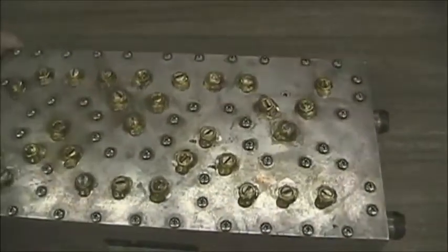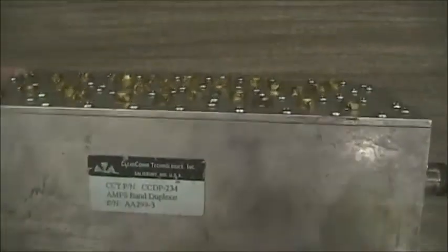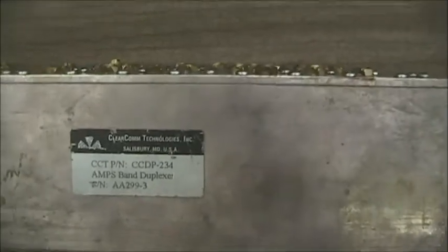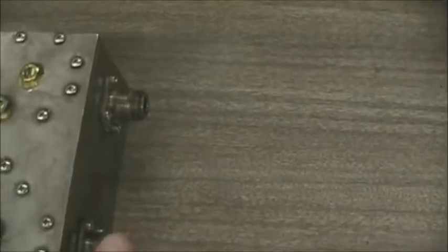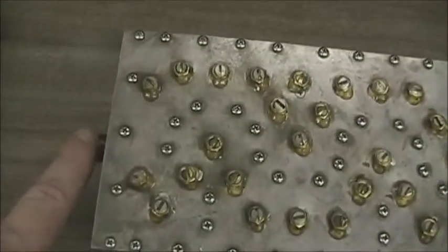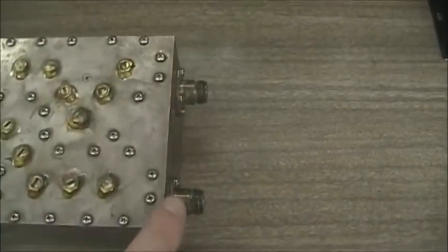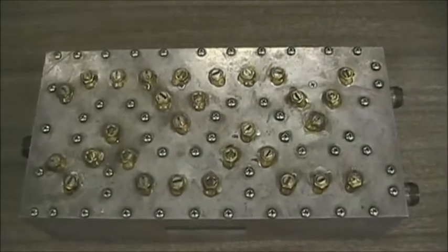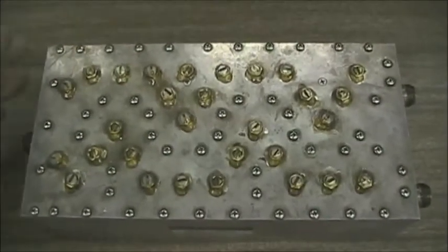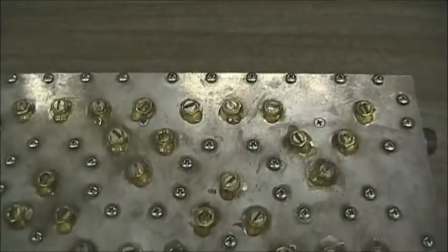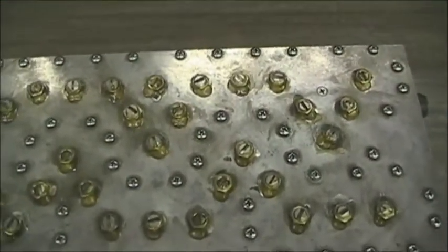I picked this up at a swap meet years ago. This was what we call a duplexer. And a duplexer is a 3-port device. We see 1 port here and 2 ports here. And a duplexer allows us to connect an antenna to a transmitter and a receiver. This one happened to come out of cell phone version 1. They called it the AMPS system. And this operates, I'll show you the data, just under a gigahertz.